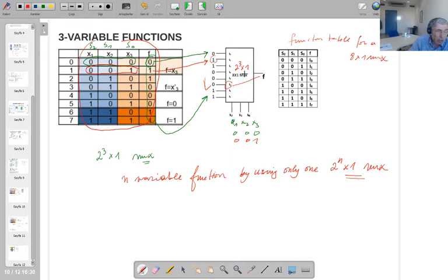So you're going to buy this mux. When you buy this mux, you don't have to find the minimal function. You can directly transfer this truth table's last column to the input of the mux, then you realize your function. So it is much faster to do the design by using this mux.